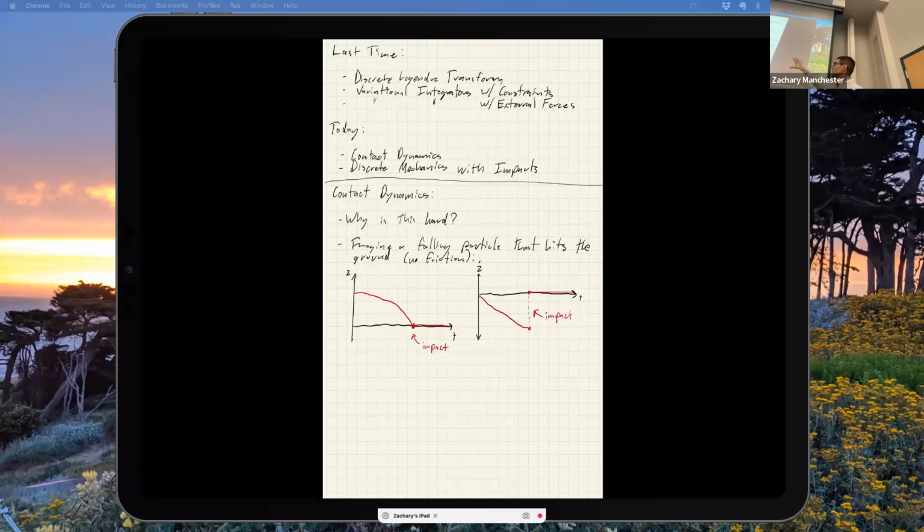So this approximation that it's happening instantaneously is an approximation, but it's a reasonably good one in the context that we live in, where maybe the fastest controllers on our robot are running at a few hundred hertz or a kilohertz. This is still happening two to three orders of magnitude faster than that at the material level. It's way, way too fast for us to resolve with anything on our robot. And so this is really what it looks like to us practically and to our robots. So that's the way to think about this.